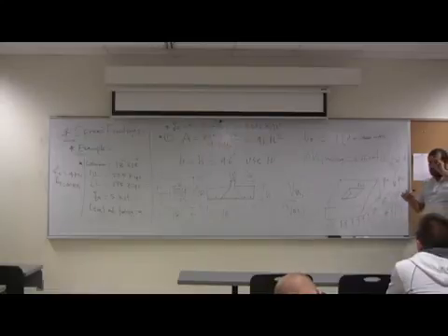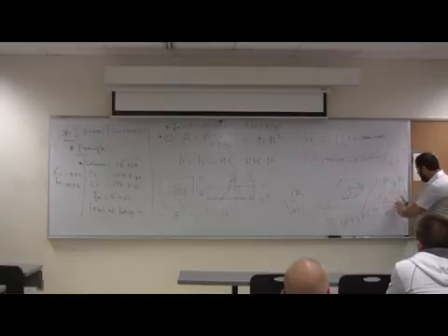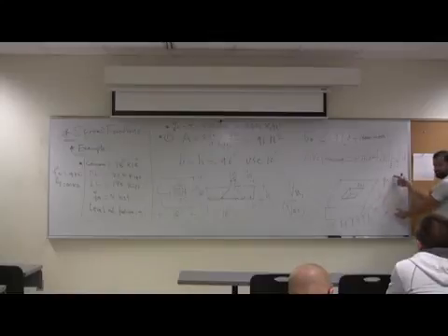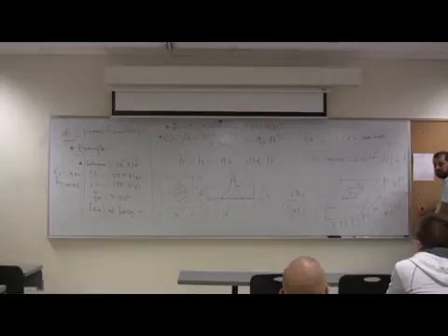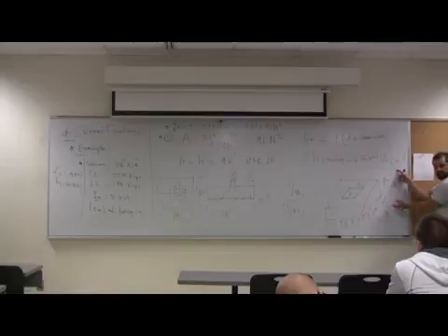So the shear stress times this area on the 4 faces gives you a shear strength to resist the difference between them. In other words, you know what's Vu2? It's P ultimate minus Q ultimate times that.